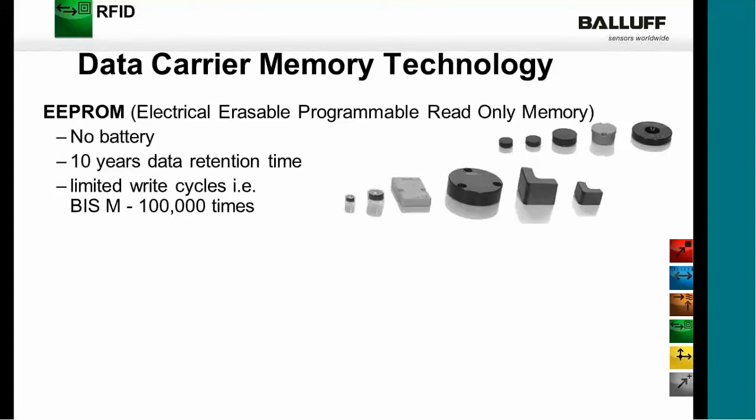There are a few different types of memory technologies. EEPROM, that's electrically erasable, programmable, read-only memory, where there's no battery. The tag will retain the data for a period of 10 years, and you're limited to 100,000 writes to the same memory area of the tag.